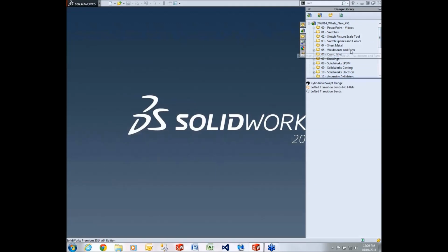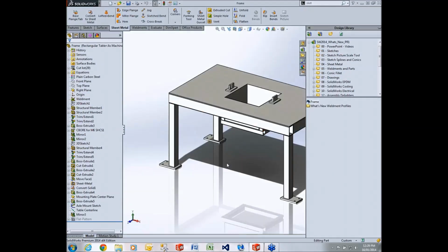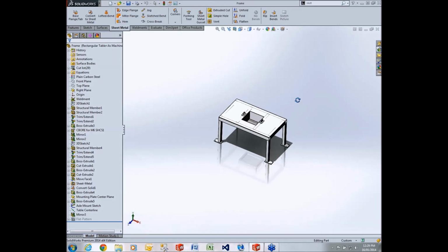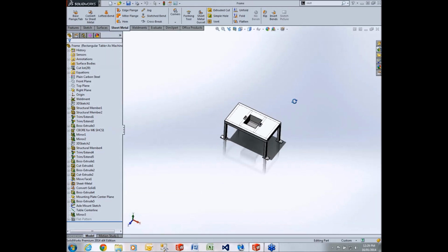All right guys, next one that we're going to take a look at is to do with parts and weldments. The first thing that I want to show you is something that might be a little difficult to show through the webinar. I'm not sure how clearly this shows, but most of you would be aware of it, and that is this bleed through of edges when you've got very thin parts viewed at a distance like I am doing at the moment. You can see almost like x-rays, you can see through the thin part and you can see the edges of the components through it.